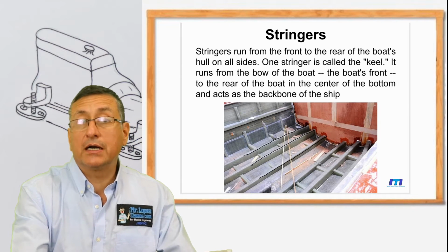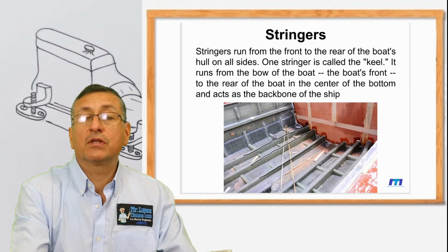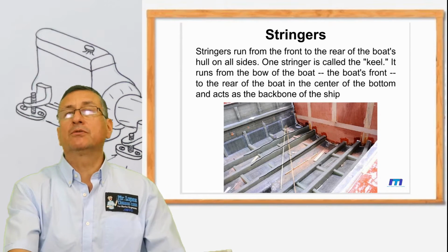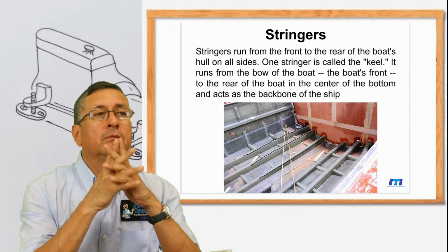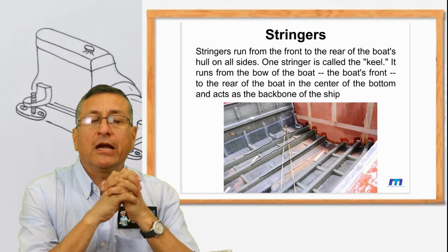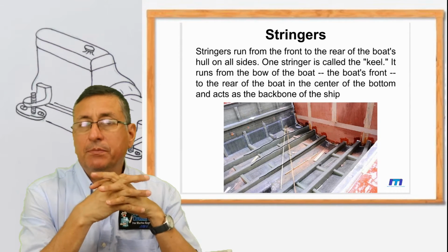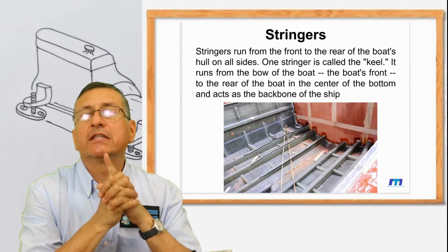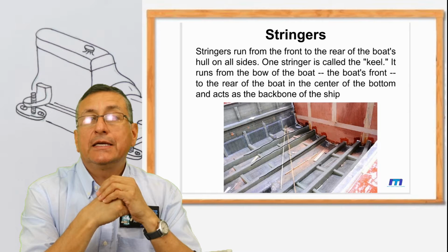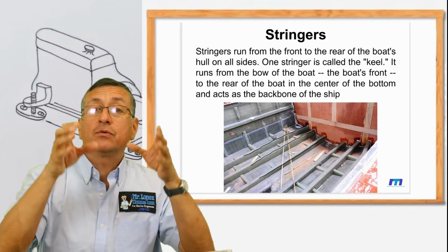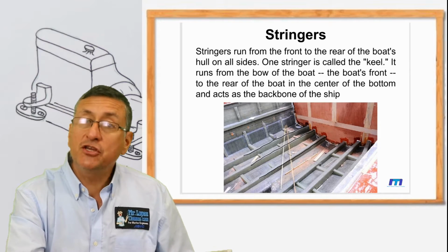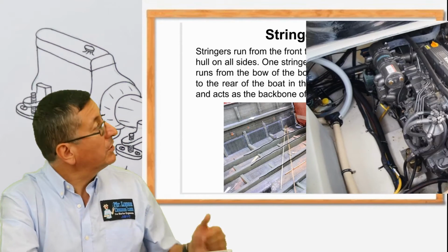The stringers are a very important part of the structure. Let me tell you something about the stringers. In my opinion, the quality of the boat depends on the condition of the stringers and the condition of the transom. Yes, remember that the engine is located over the stringers. The engine rests on the stringers.